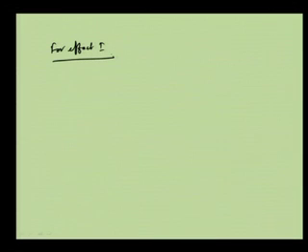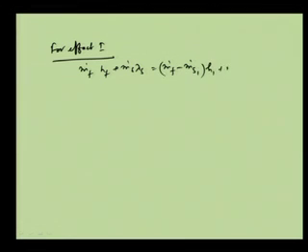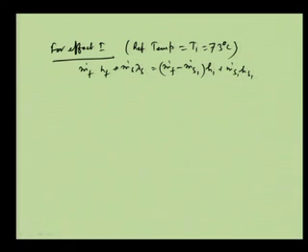if we do the calculations, then m dot f H f plus m dot s lambda s is equal to (m dot f minus m dot s1) into H1 plus m dot s1 H s1, and here we will take the reference temperature equal to T1, and that is equal to 73 degree centigrade.